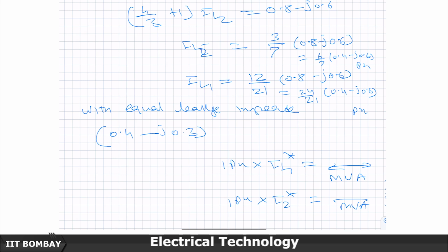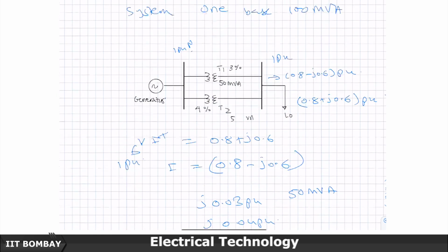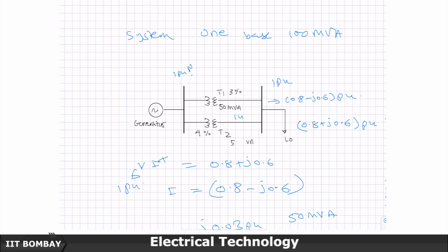You would find that this transformer is 14% underloaded with respect to this. This is not an acceptable thing, as the other transformer is running 14% above its rated capacity. This will damage the transformer, with overheating and many other problems.